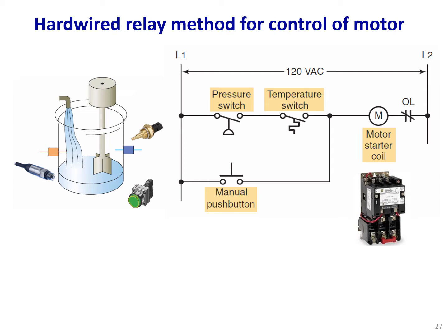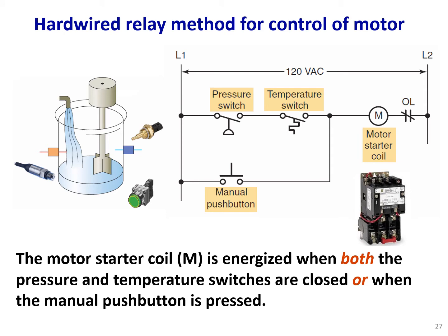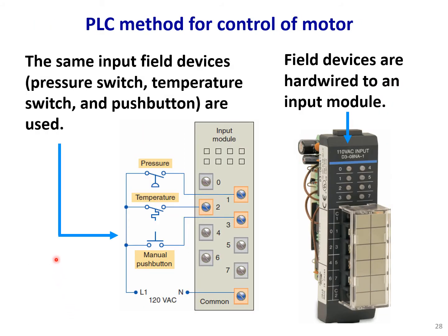Now basically we use the same methodology, the same wiring, in our relay or ladder logic programming language. The motor starter coil, or M, is energized when both the pressure and the temperature switches are closed, or when the manual push button is pressed.